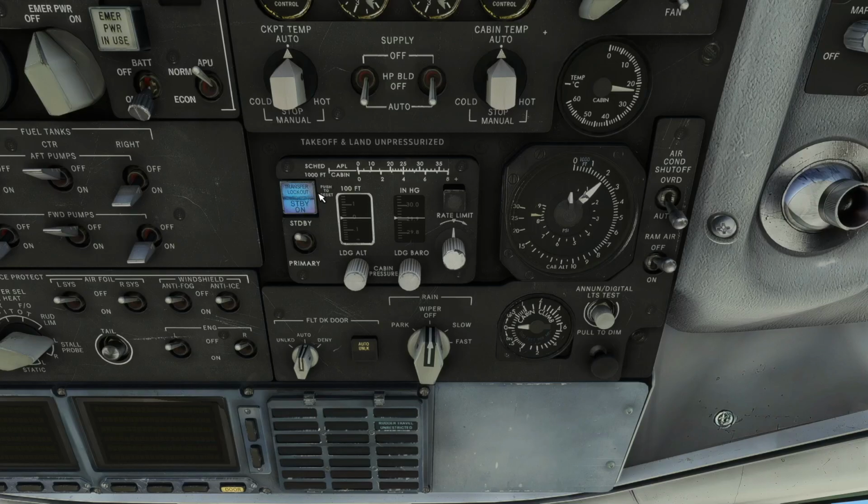So in flight, I'm going to emphasize in flight, you want to make sure you don't reset this because you don't want the transfer. You want to control manually whether it's in standby or primary. Not lit for primary, lit for standby. But on the ground, it's going to be lit like that. Even with the switch down here in primary, it's all going to be switched over because of that. And so you want to make sure you come over here and cycle this and then click it to reset. If this goes on in flight, then you don't want to reset it again, but you can switch it manually back and forth. So hopefully that explained how that works.